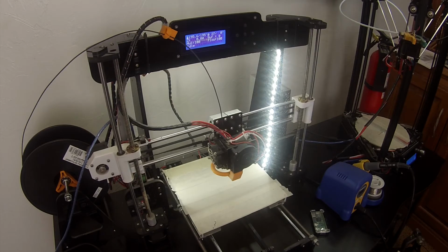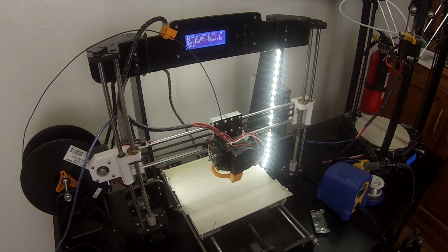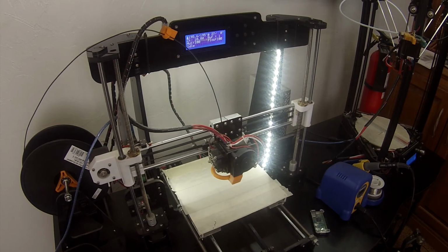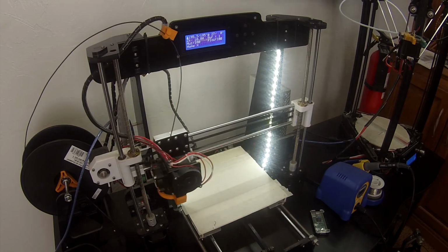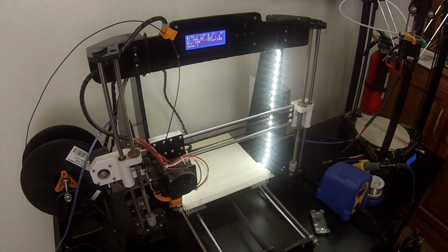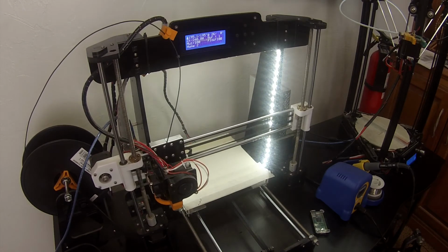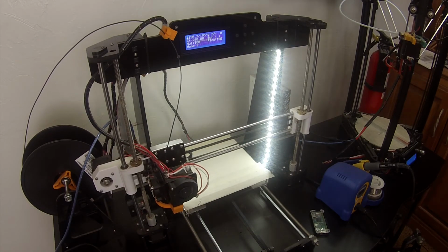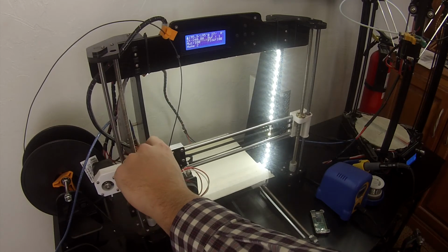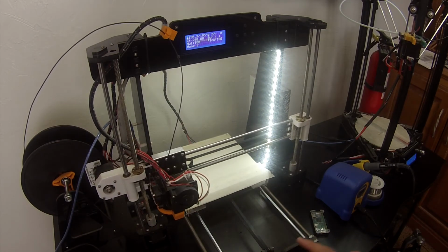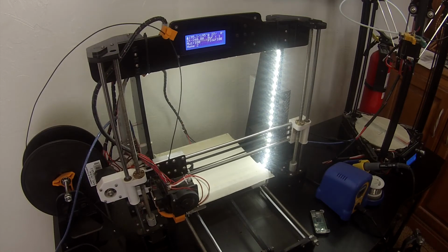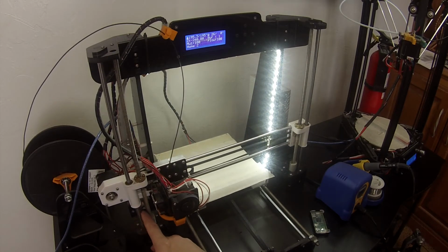The z-axis in this printer is actually fairly slow, and you'll probably find that common to many 3D printers because they only go up a small amount of distance at a time. So really at this point, you can go down, click print on our GoPro drone mount.stl, and you'll see the printer go to its writing location. It goes through the homing operation. That's what just happened there. The printer went to its limit, smashed up against that limit switch. In the x-axis, another limit switch is beneath the bed in the y, and now it's descending in the z until it clicks that limit switch hidden